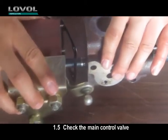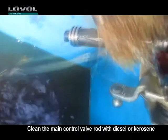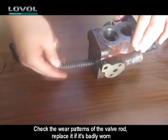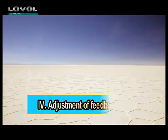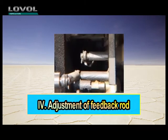1.5 Check the main control valve. Clean the main control valve rod with diesel or kerosene. Clean the distributor shell. Check the wear patterns of the valve rod. Replace it if it's badly worn. 4. Adjustment of feedback rod.